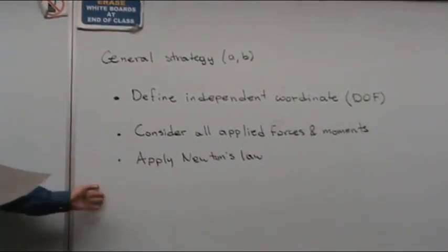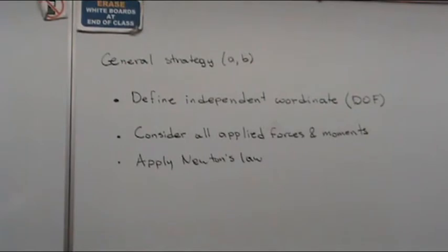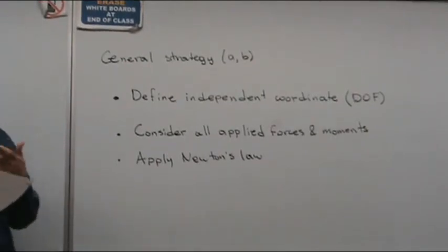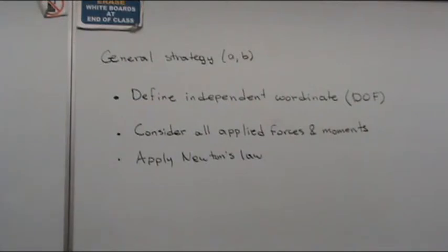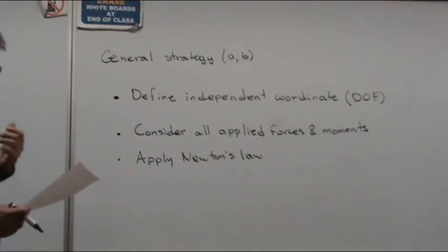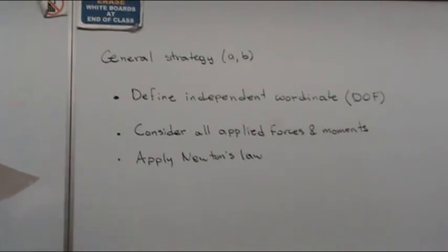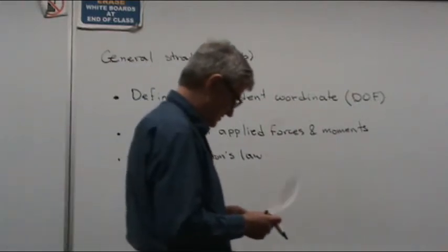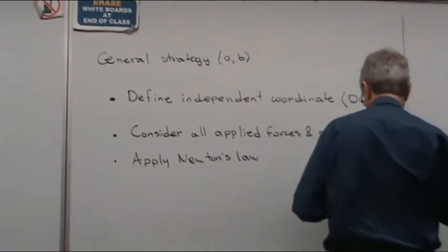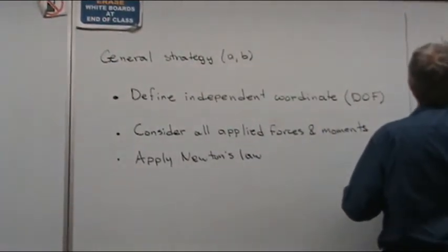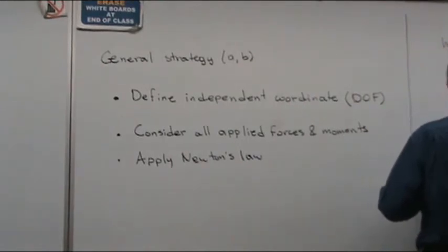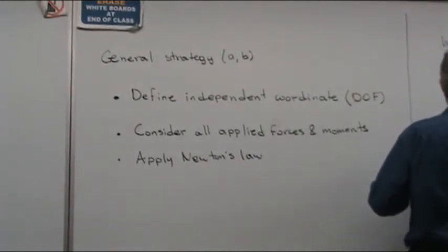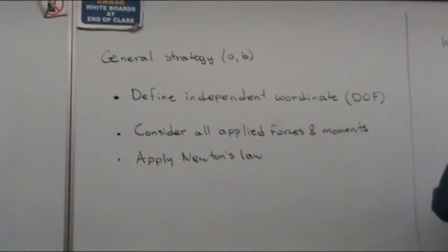Now, if we deal with dynamics, that means forces and displacements that change with time, we do not consider static forces, okay? So in order to do that, you write the equations with respect to the static equilibrium position, okay? So write equations about the static equilibrium.